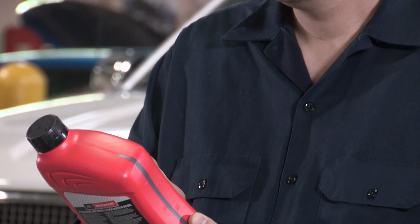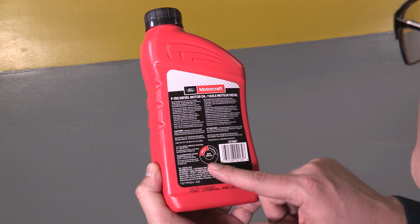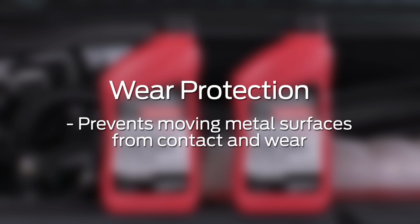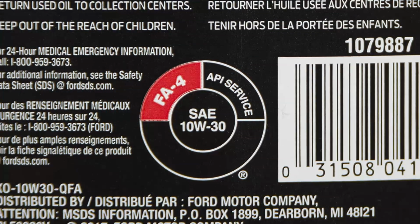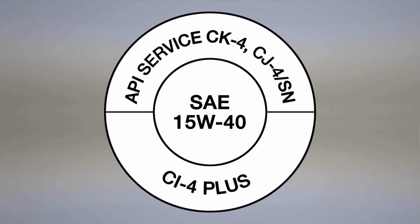Motorcraft F-150 diesel motor oil also meets the performance requirements of API FA-4 spec for the following properties. Soot control prevents deposit formation and oil thickening from soot. Wear protection prevents moving metal surfaces from contact and wear. Detergency prevents deposit formation on oil-wetted engine surfaces. And oxidation control prevents the oil from degrading and thickening. For these properties, Motorcraft F-150 diesel motor oil meeting API FA-4 specifications offers equivalent performance to API CK-4.